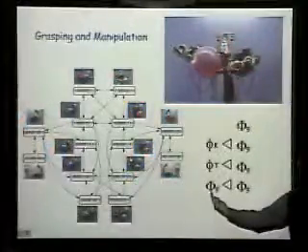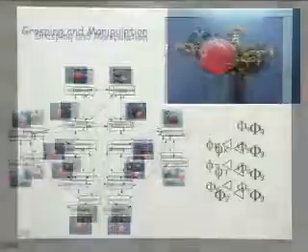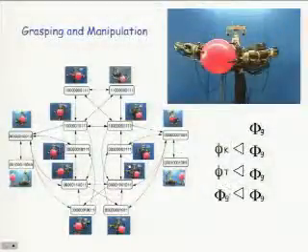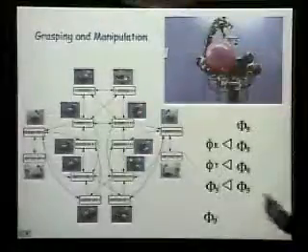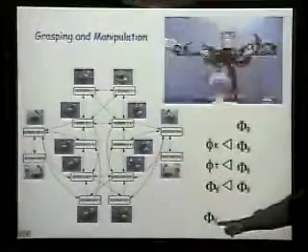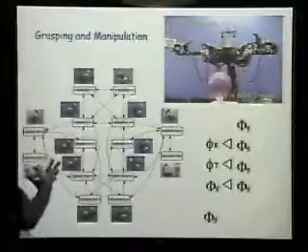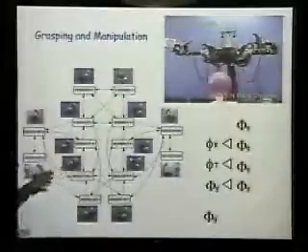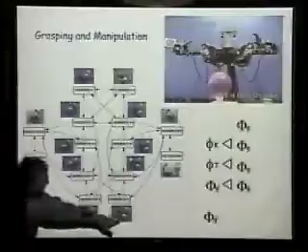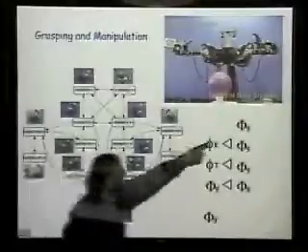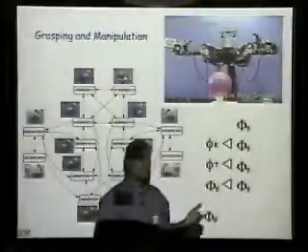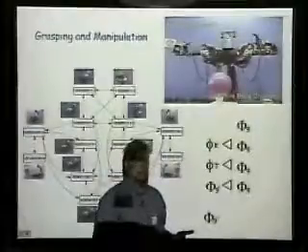The next thing is do another grasp in the null space of this grasp. There's another condition that it can formulate. It reparameterizes the grasp schema and runs that gradient in the null space of the original one, and then it can discard the first one, right? So what I showed here is essentially this transition, and there's 11 bits in this representation, still relatively small as a control representation. And all of these transitions are different places it can go that don't violate the condition that at least one stable grasp is present at all times.